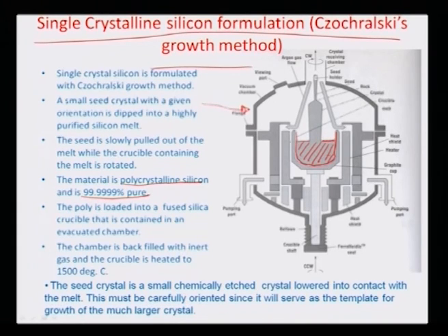and this crucible is basically capable of rotation. So you can rotate the whole crucible, and also it is inertly filled. The chamber here is evacuated using pumping mechanisms as illustrated here and here, and then you can fill the whole atmosphere of this fused silicon container with argon or an inert gas, so that it ensures the non-inclusion of material like oxygen or nitrogen into the silicon lattice.